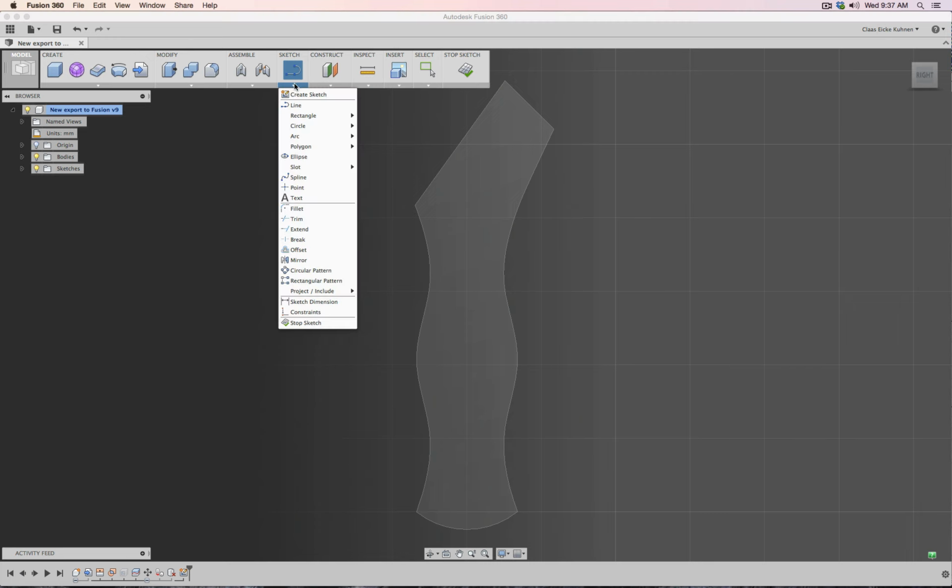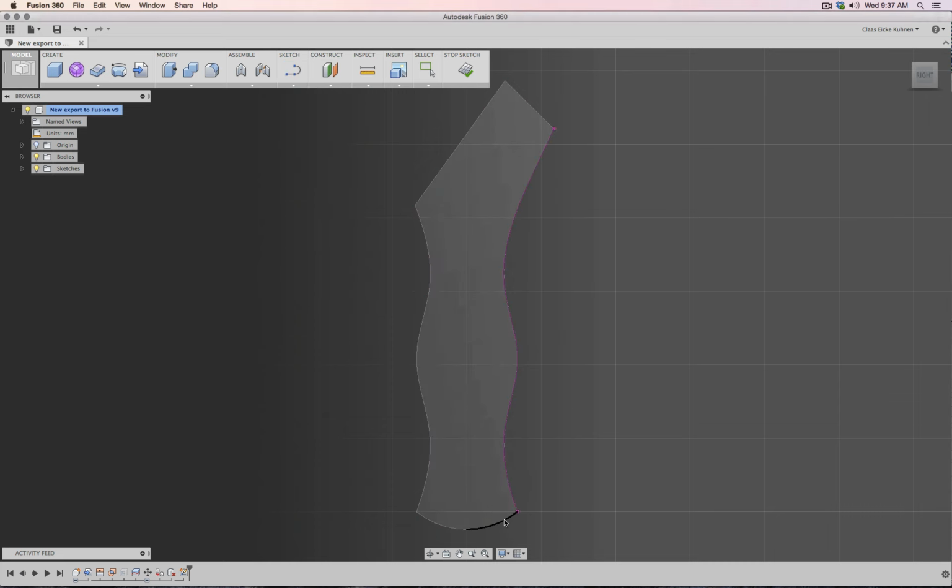So I would like this geometry to be a little bit snappable too. So I'm going to include some of those lines. So this include 3D geometry actually makes those edges visible inside my sketch. It redraws them interactively.